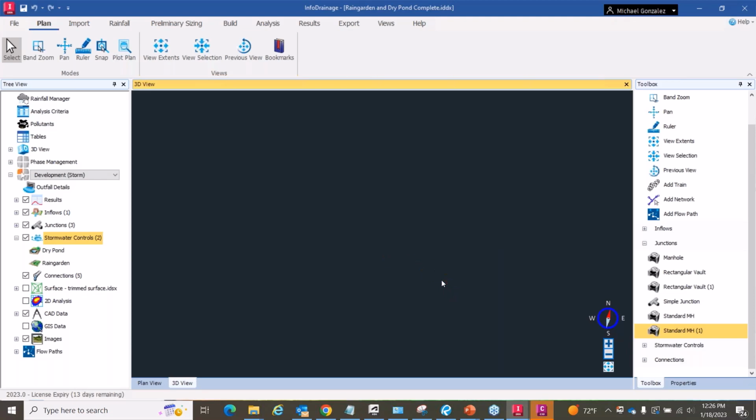Yeah, so you can see, a little bit wonky to visualize here. I'm not used to the rotation aspect of it yet, but there it is. So you can see our bypass, our trapezoidal bypass is going right over there. We have an under drain going here, it connects into it. It goes in, now falls into our dry pond area over here.